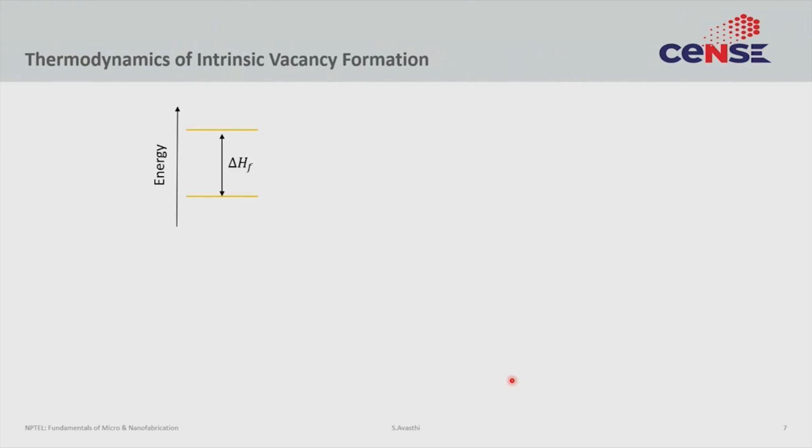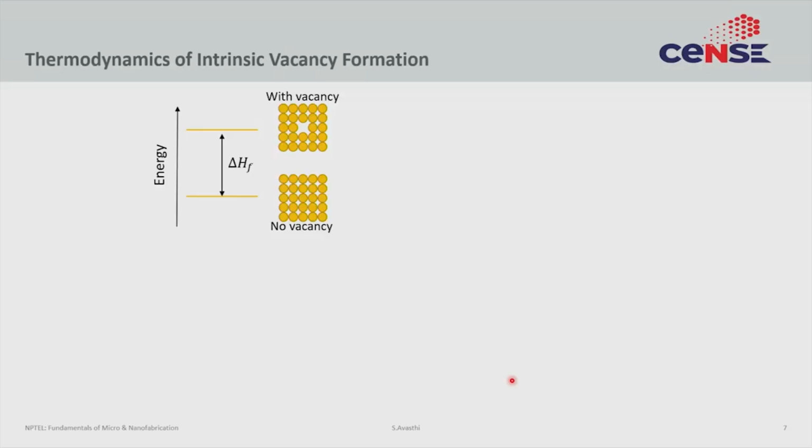Now, you would think that there should be a concept of a perfect material which does not have any vacancy or interstitials, right, at least no self interstitials and self vacancies. It turns out thermodynamics predicts that that cannot happen. Because of entropic reasons, you always will have certain vacancies and interstitials. Here is a very basic understanding of why. Supposing you take a material and you take two cases, when there is the perfect semiconductor. Now, this is the happiest state, the lowest energy state, and now you create a vacancy inside this material. To do that you have to break some bonds, you have to pay some energy price. So, that is your enthalpy. This is the enthalpy you have to pay to create that vacancy.